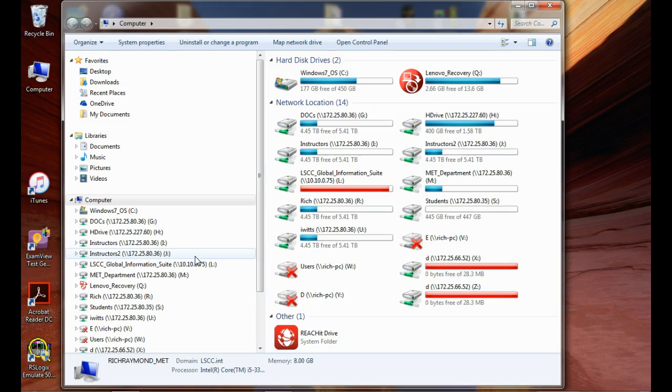And then the last thing we would choose would be what? Starts with an R. We choose the regulator, right? We made sure we need to get a regulator that can handle the current required by the load, right? And be able to drop the difference between the unregulated and the regulated voltage and not burn up,